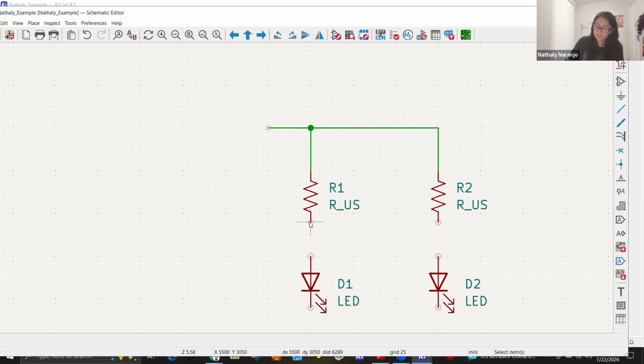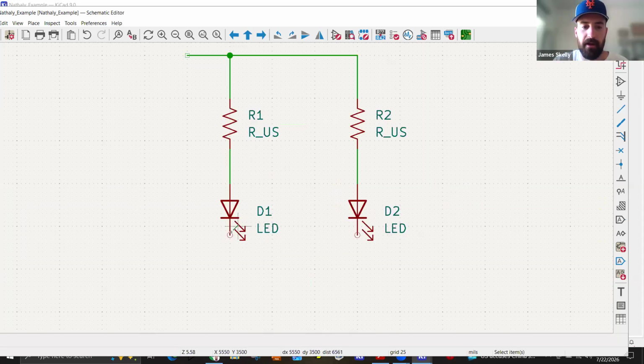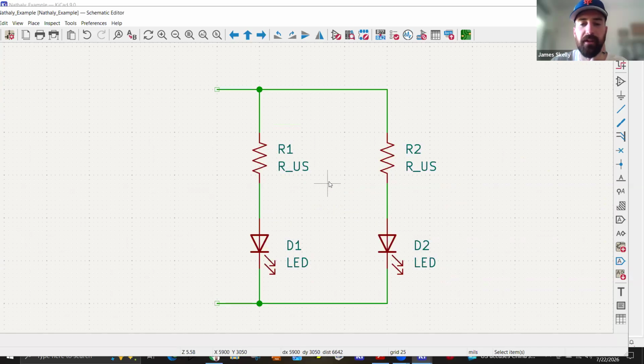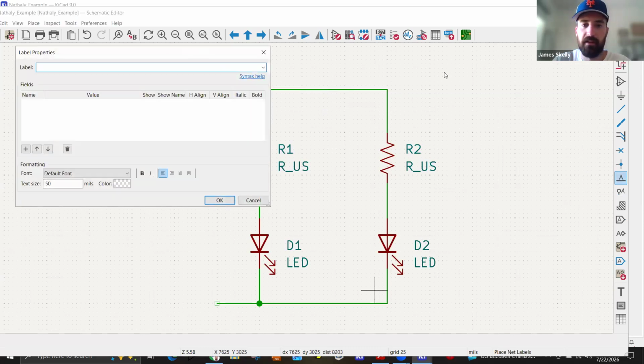Okay. So from here to here, I'll connect. From here to here, I'll connect. And then I'll make another little bottom node here. It's a very good practice to get into the habit of labeling all of your nodes. So there's this little net label. They also call them nets. I think I used this interchangeably in circuits one. If you click place net labels, you can label.